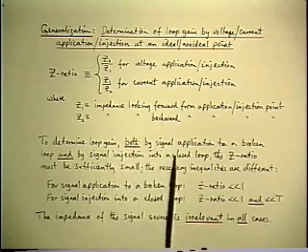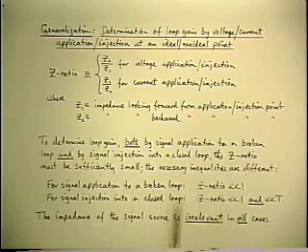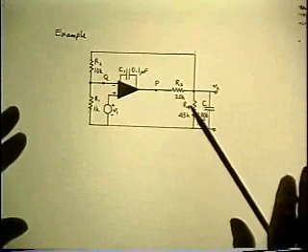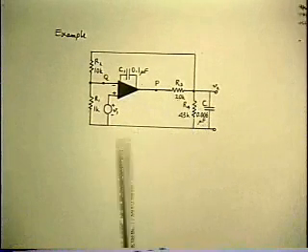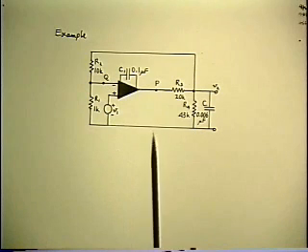But I've tried to emphasize all along that you've actually upset the loading when you do that, and it gives you the wrong answer unless the loading is negligible, which is the same thing as saying you have to meet these inequalities. And just to drive that home even further, let's go back to this example we already used initially to introduce the technique of loop gain measurement by signal injection.